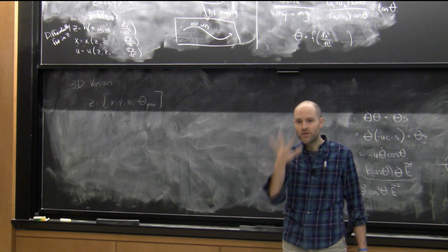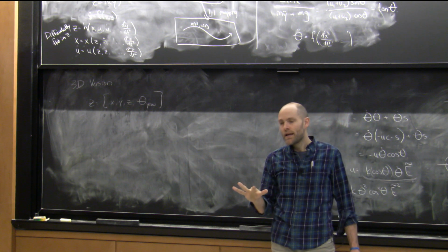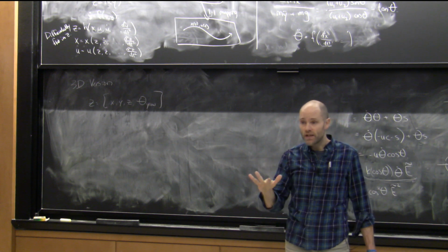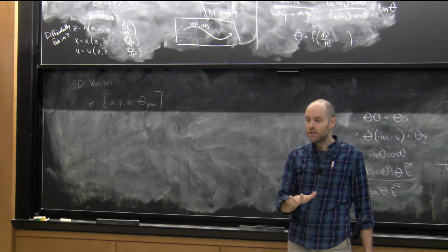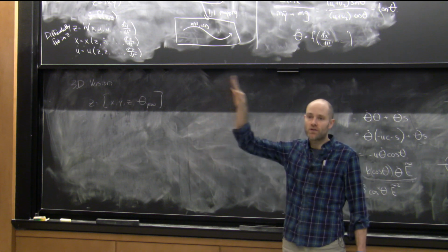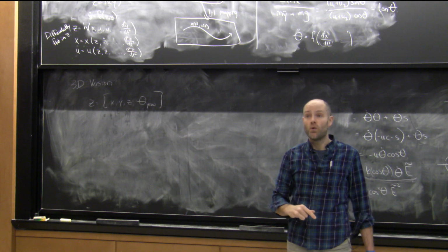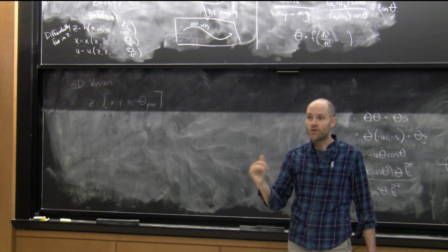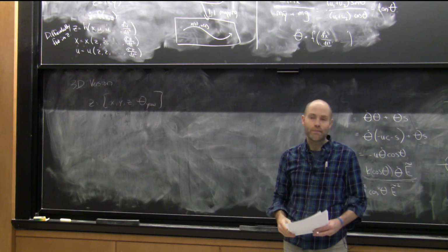They could be exactly joints, or they could be something more task general. And in the partial feedback linearization case, that can lead to stabilizing controllers, especially when coupled with Lyapunov. Or in the trajectory case here, it can be that trajectories of those M coordinates can imply trajectories for the whole space. That's sort of the opposite way to leverage that idea. Okay, we'll do computational Lyapunov next week.